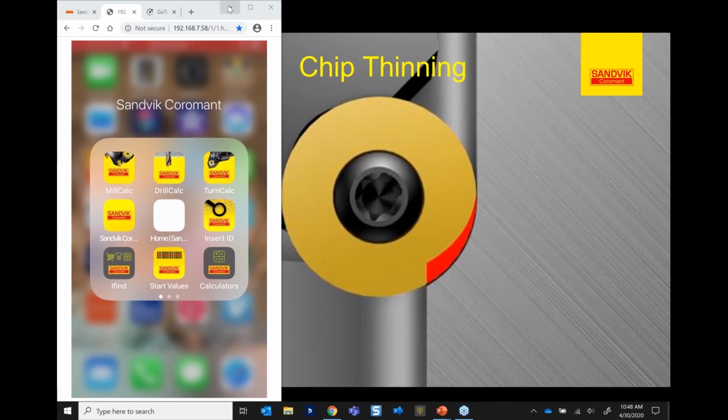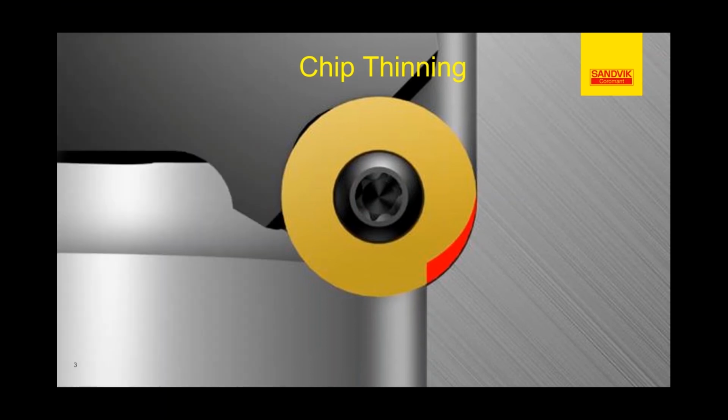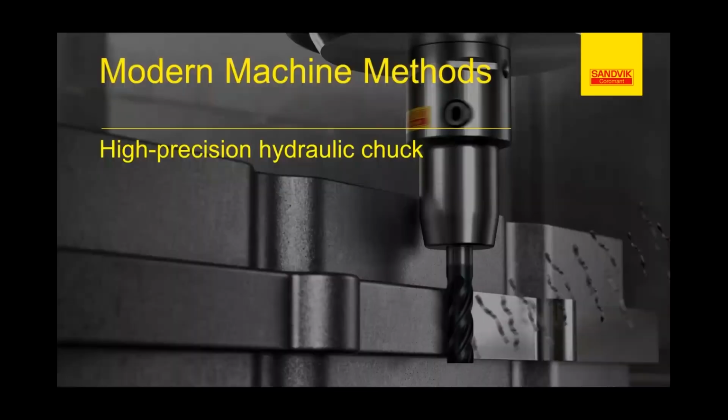Before I do that, though, I want to go back up here and show you what a hydraulic holder looks like in action. When you look at a hydraulic holder, we're using this one with high feed side milling. You can see down here, we're using a very large axial depth of cut and a very small radial depth of cut.